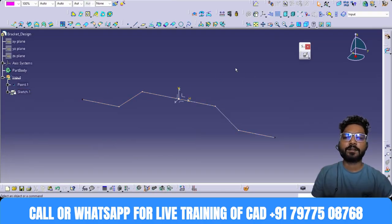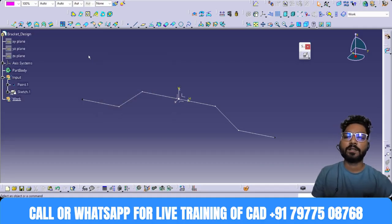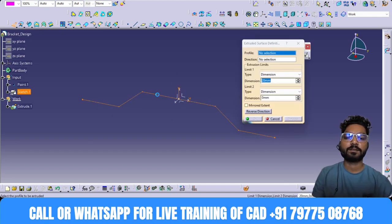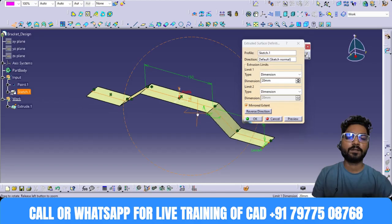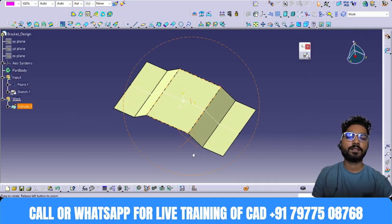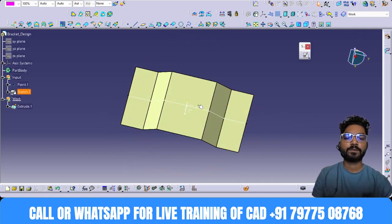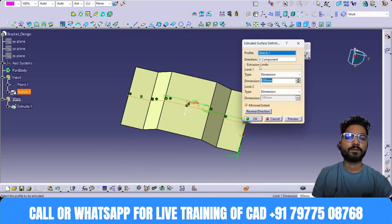So the sketch is ready. Here we'll insert one geometrical set as work, and in the work we are going to extrude it. This is my extrude command. You can select it. We'll extrude in the direction of X, by 100 mm on both sides. So this is currently 200. Or extra also, we can extrude 150.